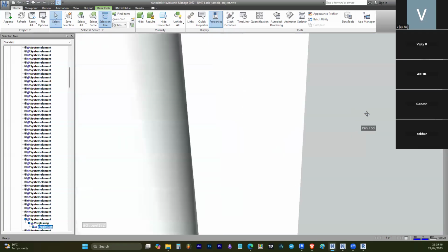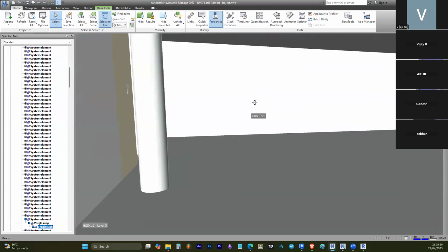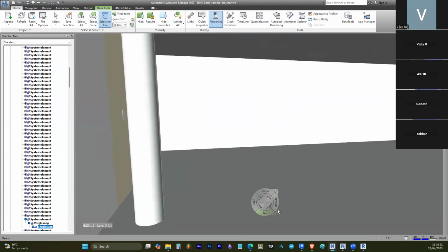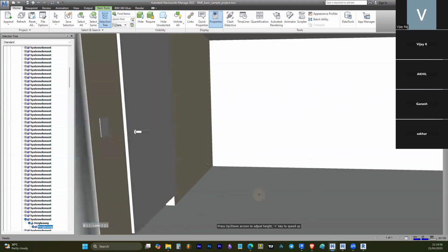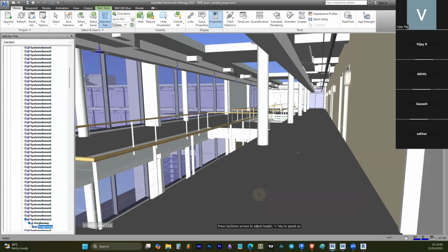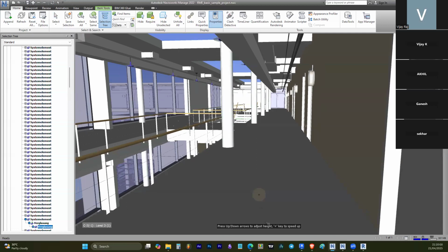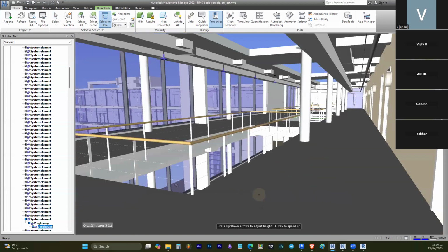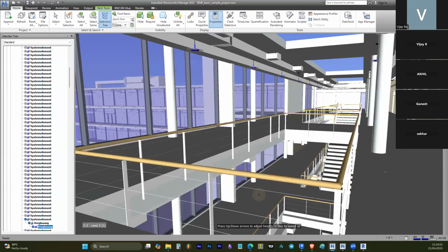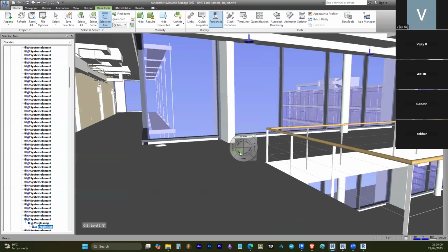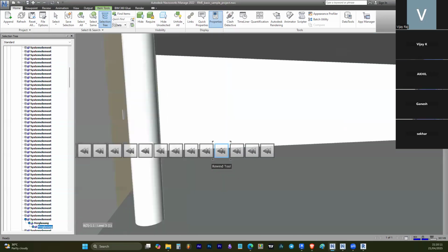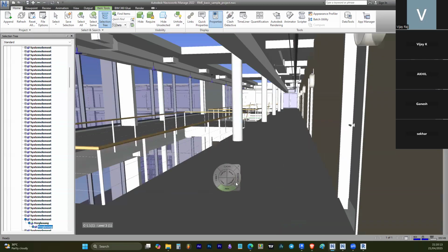So I want to navigate around it. That means I can press W for the shortcut, and I get the navigation wheel, and I am running around this. So here I am seeing currently some pipe is going through, and also rewind. Here is the option rewind.